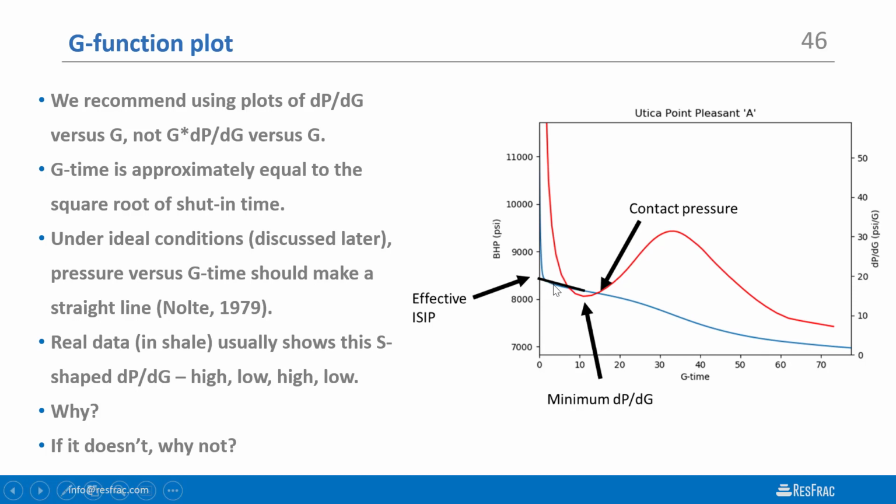And so after tens of minutes, hopefully, the pressure you're measuring in the well is now close to the pressure in the fracture. Now, in a worst case, that pinch point could theoretically totally seal off the connection from the far field fracture to the well. And if it did, then you're toast. You can't measure anything. So you should be paranoid about that. And if you get weird measurements, that could be the cause.